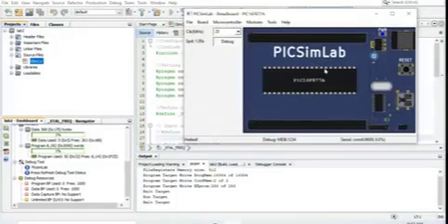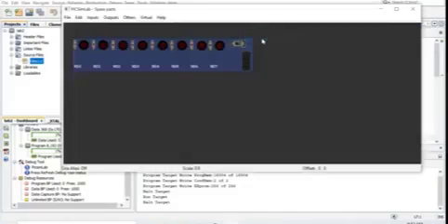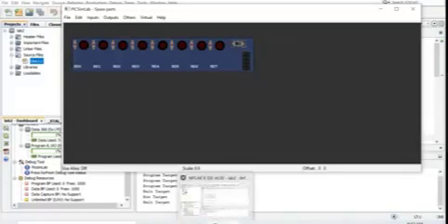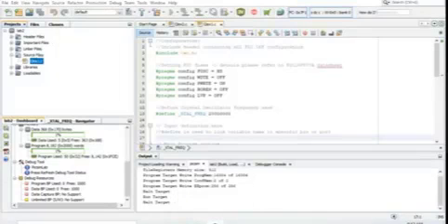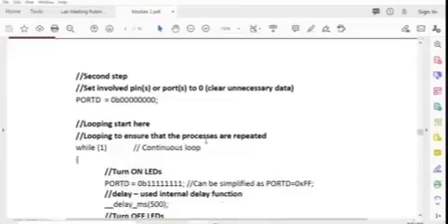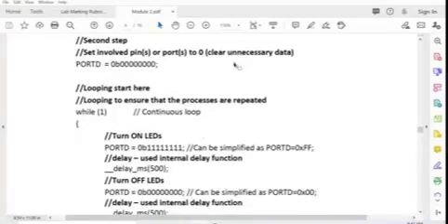And then you go to the Fixing Lab window, then do the same thing. Make sure that you check everything. Clock must be 20 megahertz, and this debug button is pressed. Make sure that the connection exists between these two software, and then the module also. The module here, we need to use output from port D.